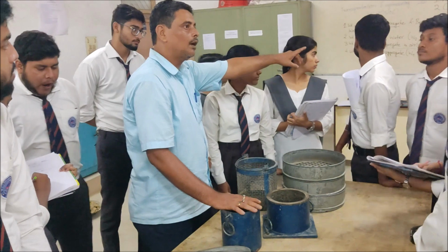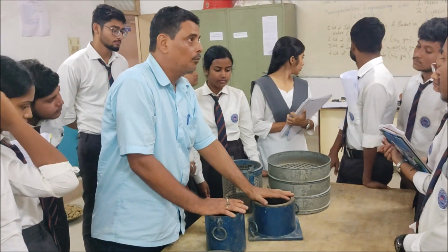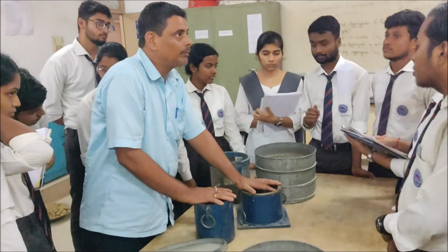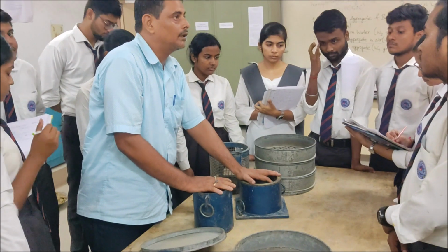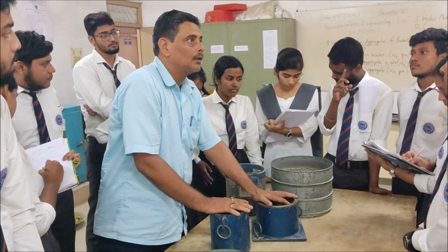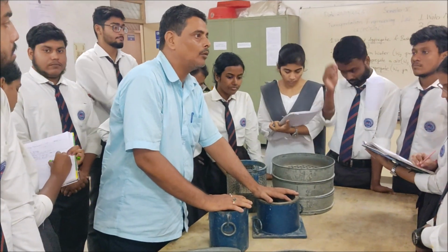We will take the mold to our CTM machine. There we will apply the total load of 40 ton in 10 minutes, and the rate of loading will be 4 ton per minute.